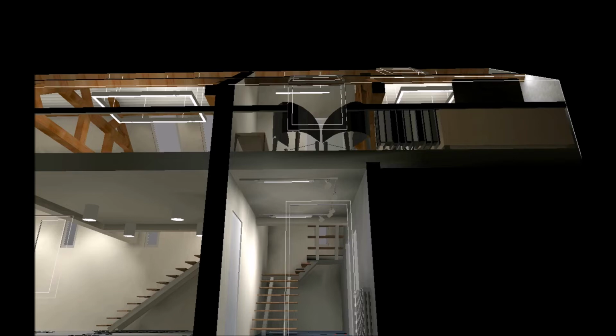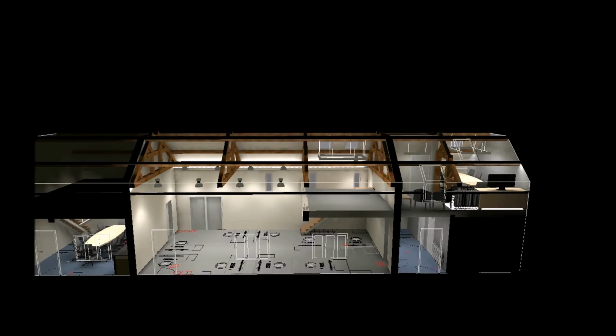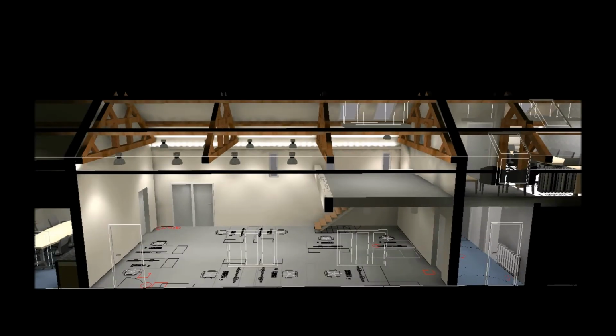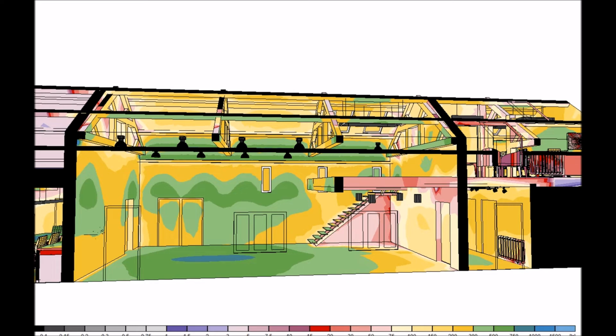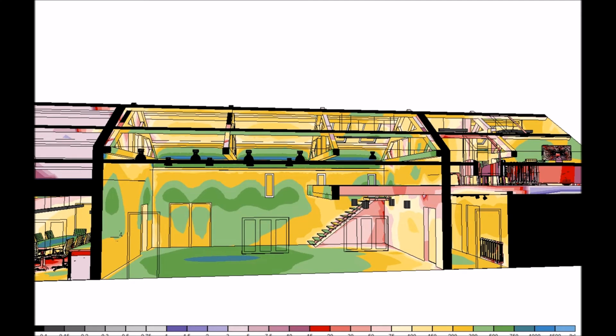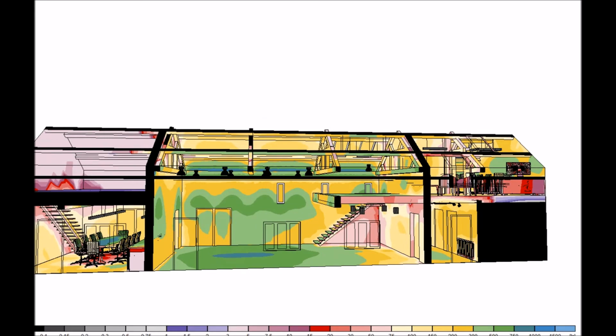And that's about it as far as the look of the building, the lighting for the building. So I will just click onto light levels mode very quickly just to talk you through that. 500 lux is this dark green, 750 lux is the blue there. So the lighting level for the main technical area, when I run the calculation specifically, is good. It's around about the 500 and between 500 and 600 as an average. Glare was all within regulation, so that is all good for that area.